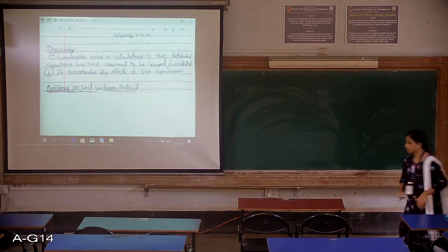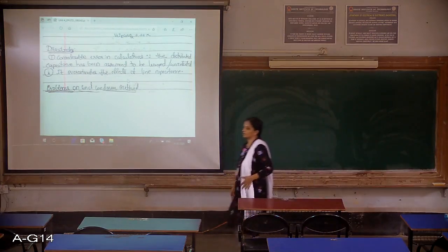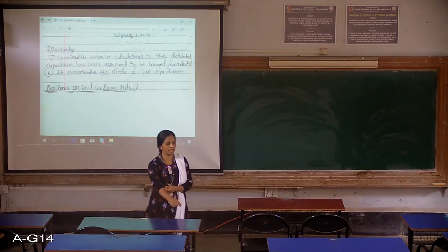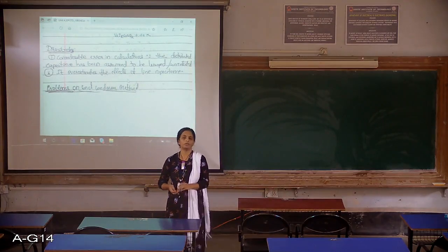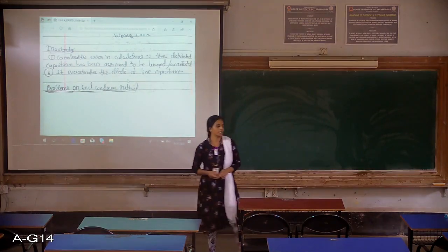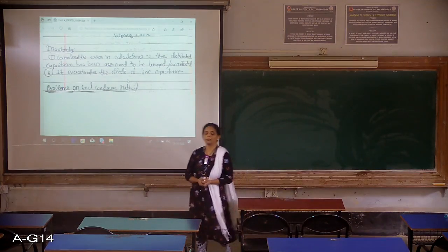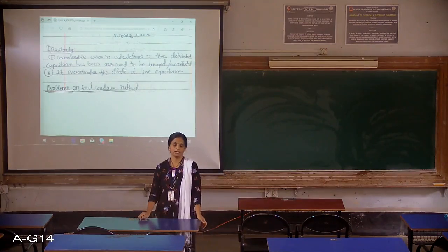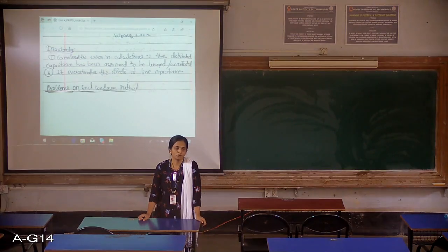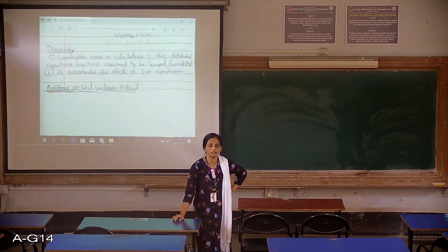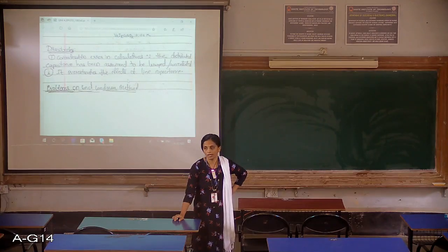Good afternoon, dear students. So I will just highlight what we have covered in yesterday's class. We started with the performance of transmission lines. We categorized the transmission lines into short lines, medium lines and long transmission lines. Up to 50 kilometers, they were grouped under short lines. 50 to 150 kilometers, we grouped them into medium lines, and above 150 kilometers they are considered long lines. Even the voltage range was discussed.